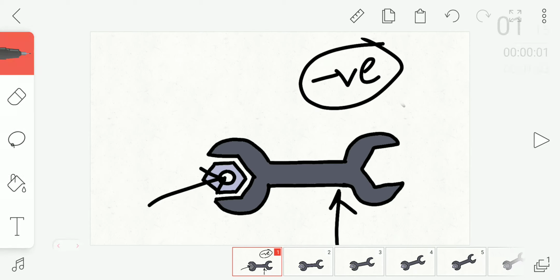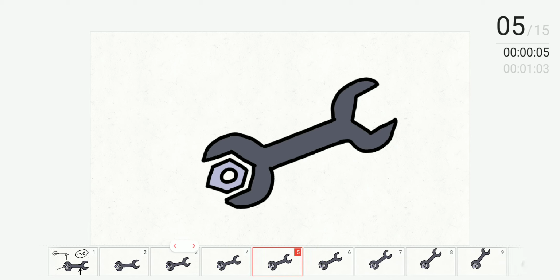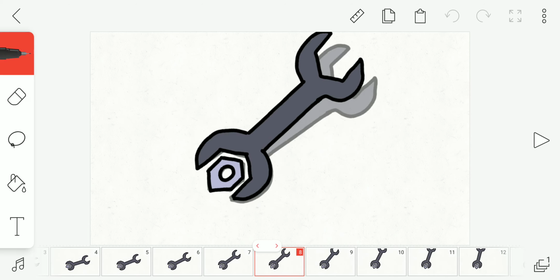So when I apply force like this, this is the force being applied on the body. This is the point where I require the moment. This is where I'm applying the force. When I apply the force, the body starts rotating like the wrench. Slowly the wrench is rotating in anti-clockwise direction, and it is certain that this point will experience an anti-clockwise moment, which can be taken as negative. If you take this moment as positive, you have to take the reverse case as positive.